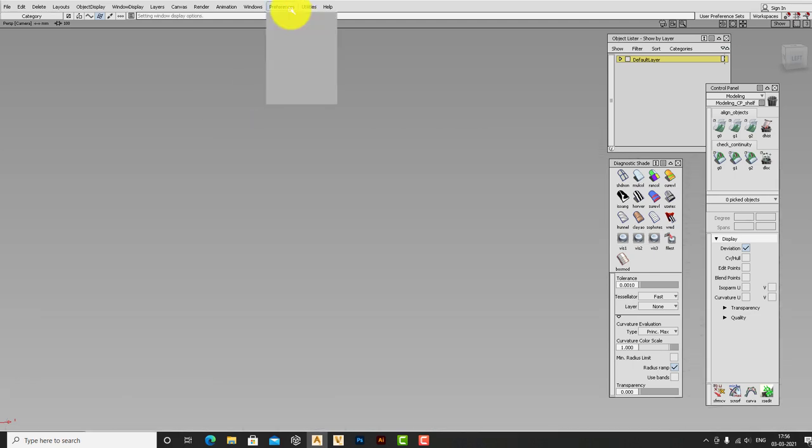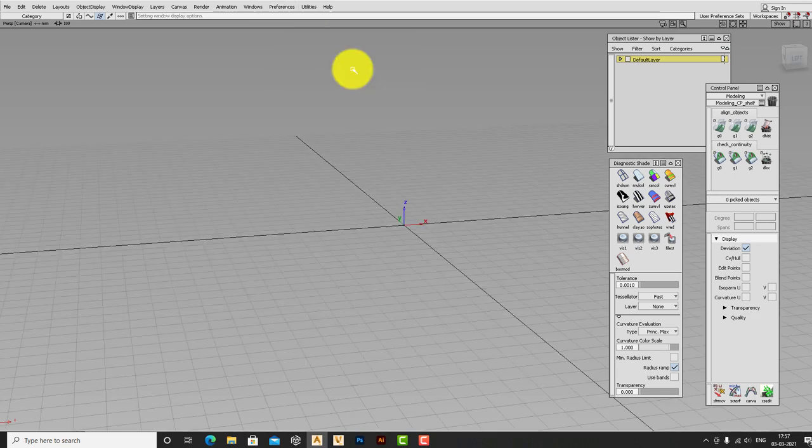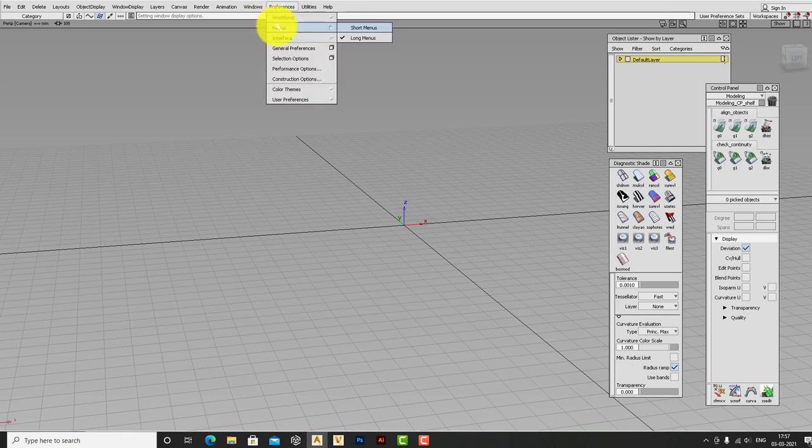Now for instance if I have this off and I type G, it won't work. It will just come into this enter menu item pick options. It will just go on typing in this. So to avoid that, you always keep this toggle single hotkeys on, so your shortcut keys will be working.